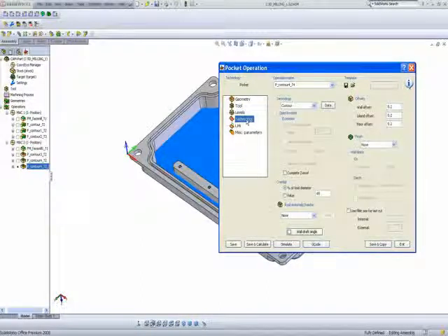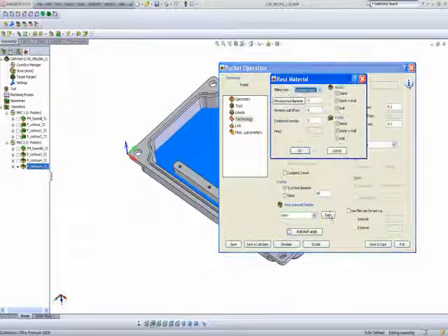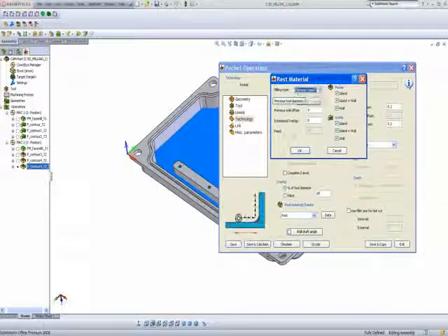In my technology field, I will use now something new called rest material chamfer. With rest material, I can tell it I want it to go into rest area, which means I only want it to work in those areas where that previous tool could not go into. In my data area, we'll be working on separate areas. Around profile, I will talk about later on.